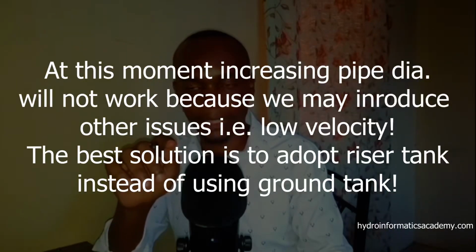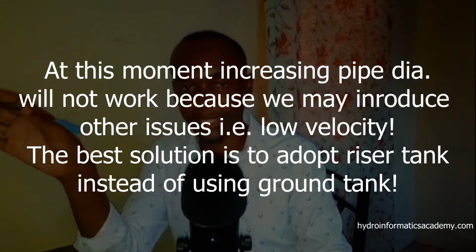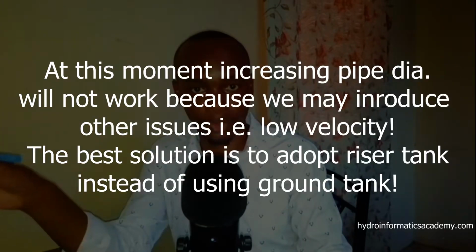Now, what we need to do, we have two approaches: either increase the pipe diameter or change the storage tank. Remember, our source here is a storage tank. We can play with the storage tank to see if we can increase this residual pressure, especially at the end point. Because as of now, the storage tank that we are using here is the ground storage tank.